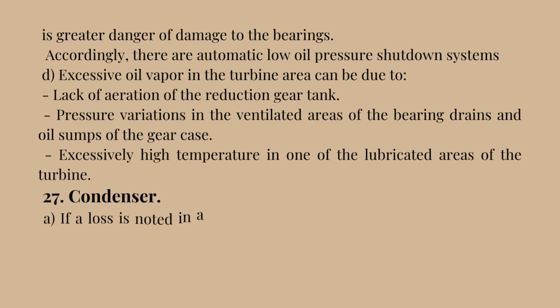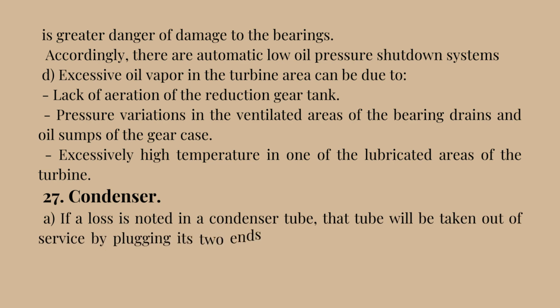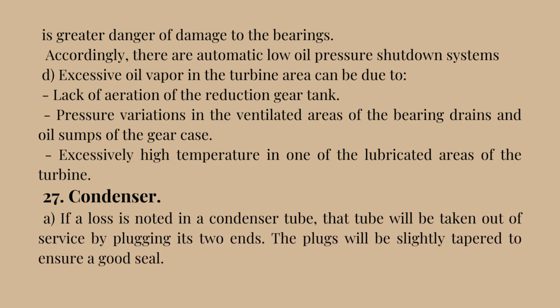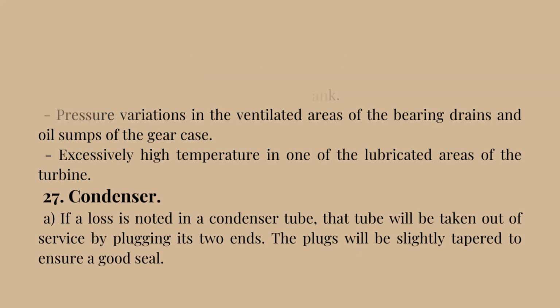27. Condenser. A. If a leak is noted in a condenser tube, that tube will be taken out of service by plugging its two ends. The plugs will be slightly tapered to ensure a good seal.